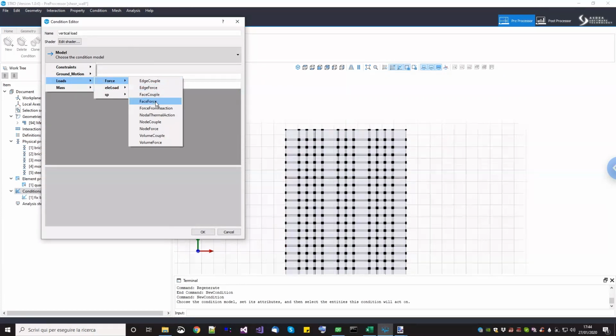And you may ask, okay, but OpenSees doesn't have distributed edge force on surfaces. Yes, but in STKO, we did it in the sense that the user inputs a distributed load over an edge, and then STKO does the nodal lumping automatically, so that the Tcl file in OpenSees will have a lot of equivalent nodal loads. So this is quite convenient.